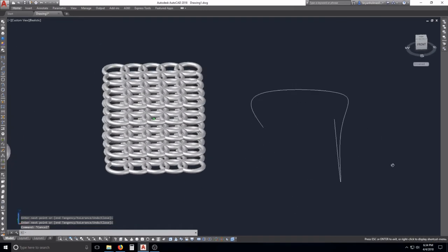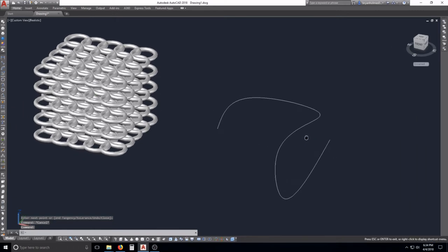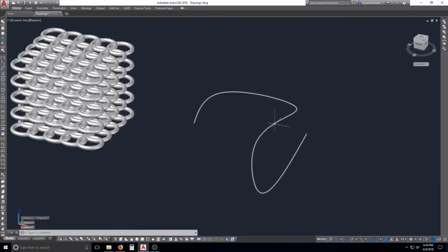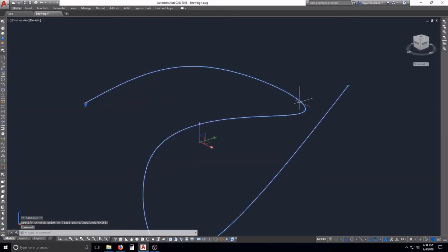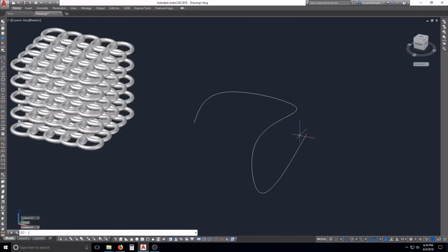See, the key thing you've got to pay attention to, guys, when you do this, make sure that whatever shape you're drawing won't touch itself as it passes by here. Say if this line was really close to that one, when it would go to make the shape, and if the shape had a big enough diameter, it wouldn't be able to do it because it doesn't know how to calculate that. So I think that was my problem before. Cross my fingers. Hopefully we'll be able to get it right this time.